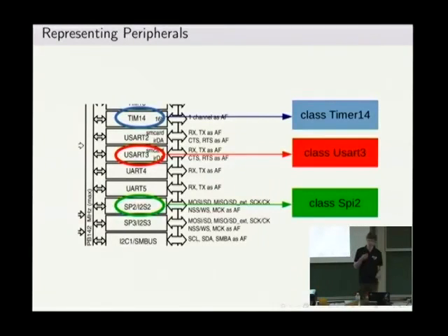So now you say, well, this is a lot of things to do. Why can I not just have one UART class and then give it the index and say, create a new UART1? Well, this is a little bit error prone, because you have to imagine you're running on a microcontroller, so there's no way to report errors. On your regular system, you can just do an assert and your program crashes with an error message or whatever. But on a microcontroller, you have no good way of telling the user there's something wrong.